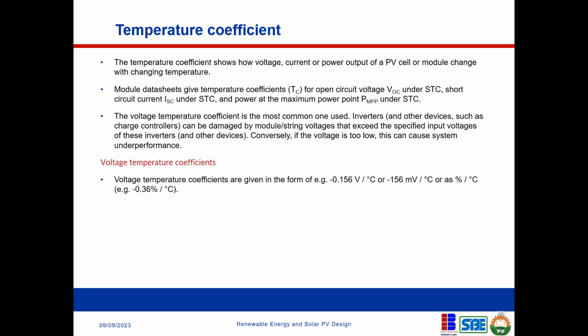Okay. So now, voltage temperature coefficient. What this simply means is, to what level will the performance of this PV module reduce if temperature increases by 1 degree centigrade? So if you increase temperature by 1 degree centigrade, how will it reduce the voltage of the panel? If you can determine that, you can actually see how the power will drop if temperature keeps increasing, right?